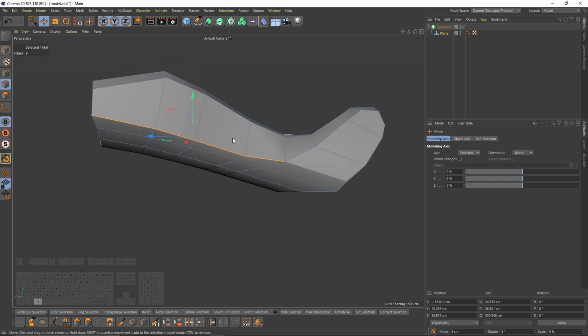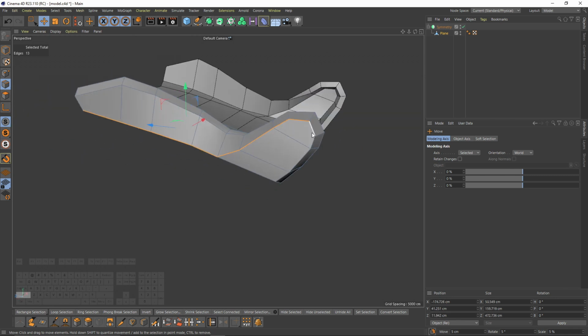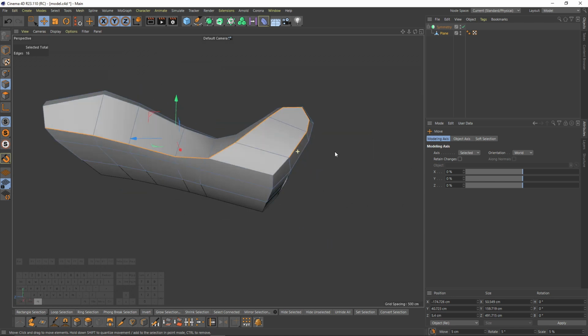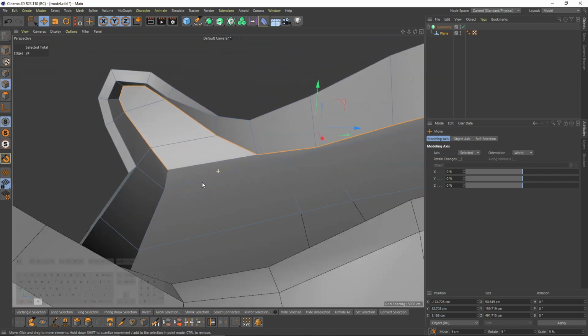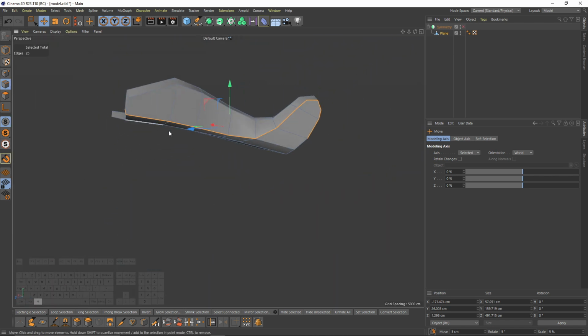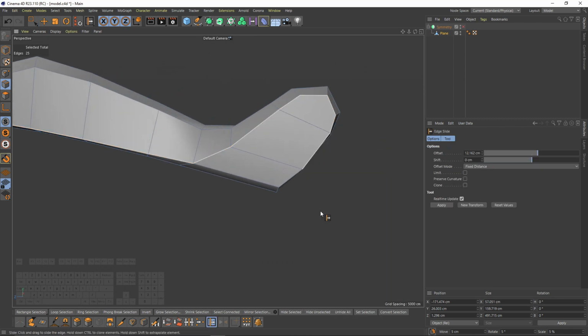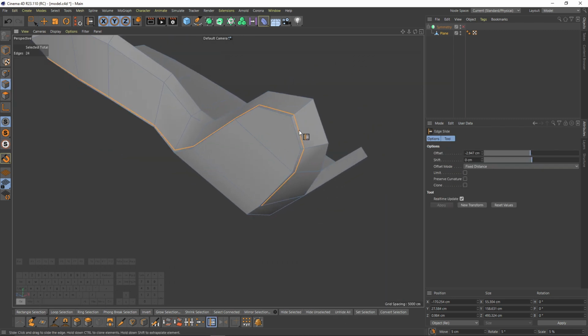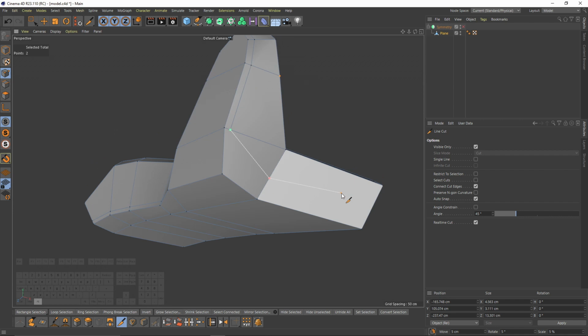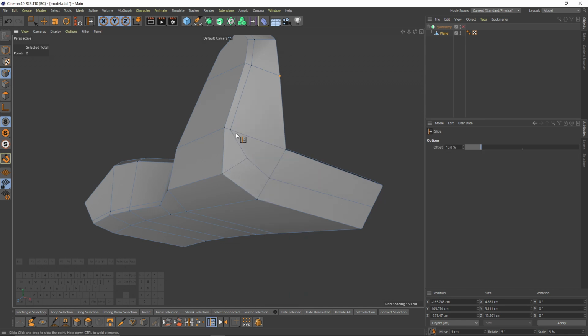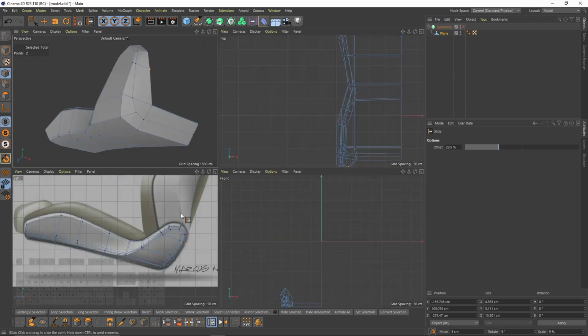First, let's double click on that edge loop. Here and here. Also, let's select the inside. And select slide, press Ctrl and move. Then I will select line cut and finish that cut. And also I will enable single line. Then I will switch to slide tool and move these points because that part is not that sharp in the reference image.